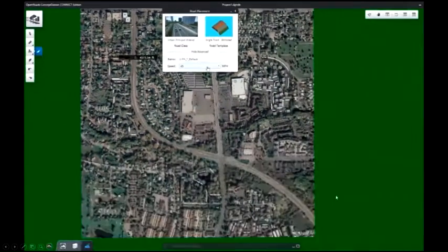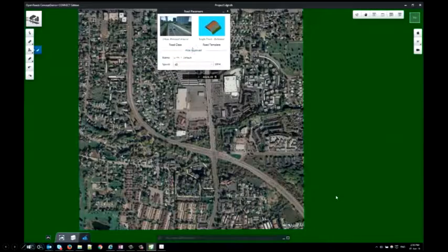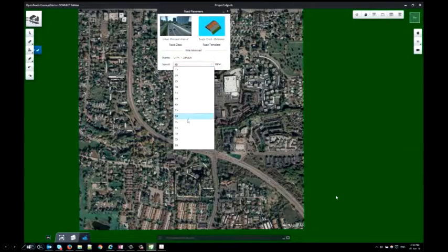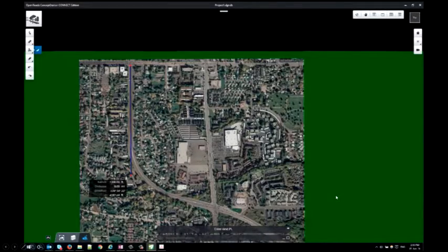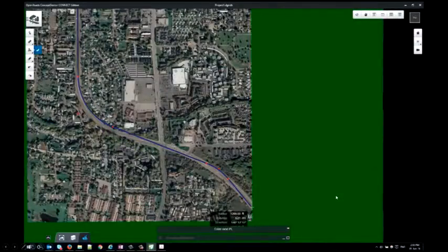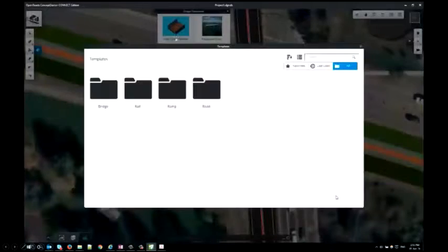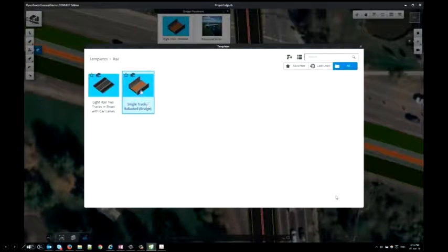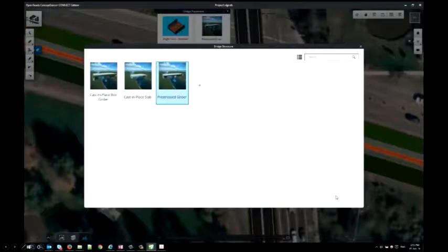We've also added some tools for tracks. So this is in the latest release, and this just gives you the ability to, just like you would lay out a road, lay out track alignments, and instead of using road geometry, it uses track geometry and typical spiral types. And you can use this with the bridge tools.